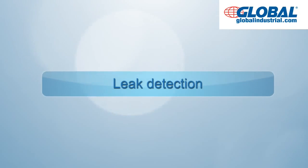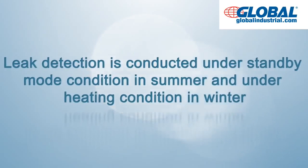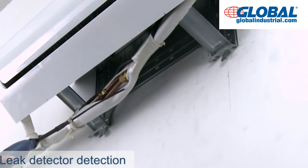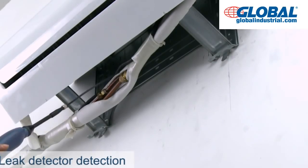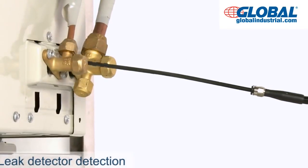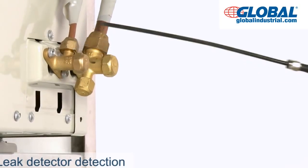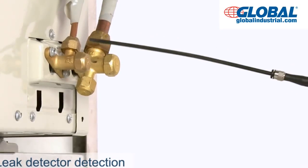Leak detection. Leak detection is conducted under standby mode condition in summer and under heating condition in winter. Leak detector detection. Probe moves around weld junction at slow and uniform speed of 1 to 2 centimeters per second, and the probe is kept at the length of 0.1 to 0.2 inches away from the weld junction. It turns 1 lap around valve ports of high pressure valve and low pressure valve respectively. If leak alarm occurs, remove probe for retesting and confirmation.